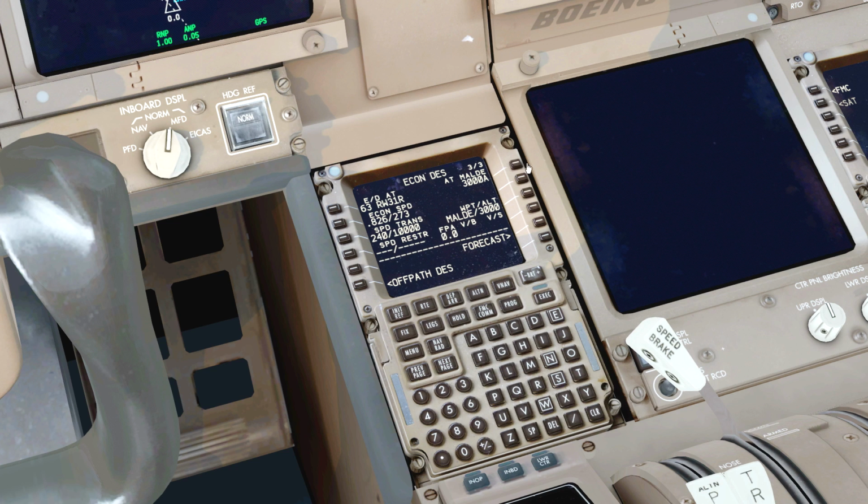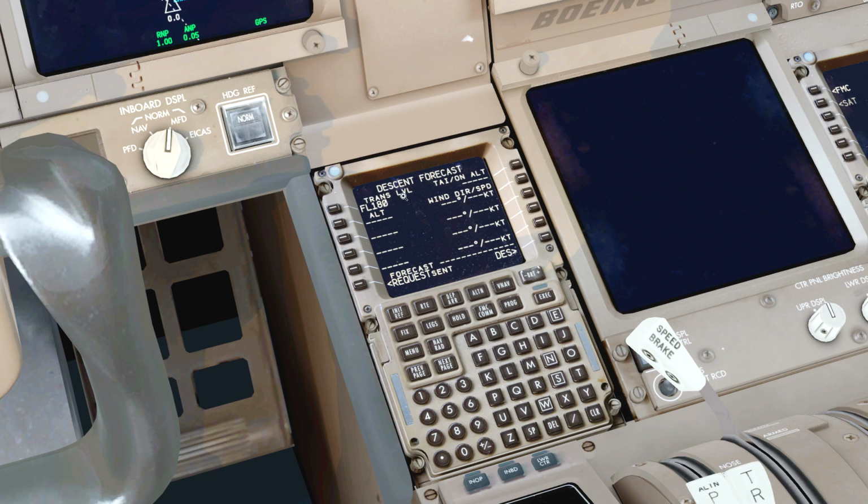It's kind of the stuff that you can enter during the arrival. You don't have to enter per se, just make sure that the speeds are okay for your different altitudes. Forecast page may allow you to set a transition level, which is 180. And the next thing that I want to do though is load some wind data, and especially on very long flights this is very important.